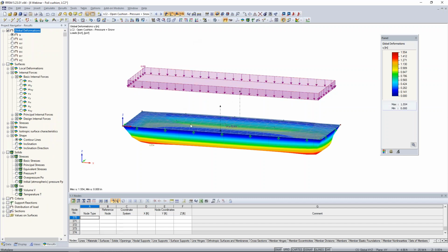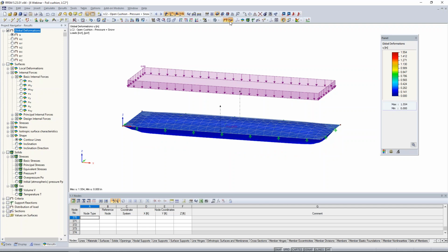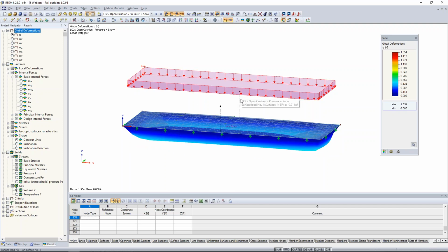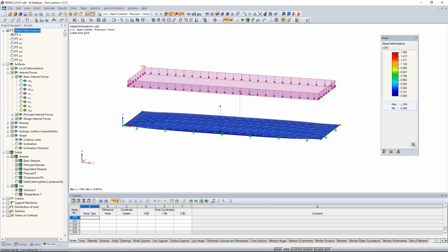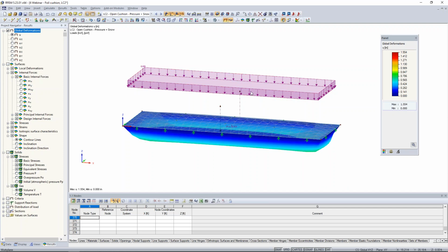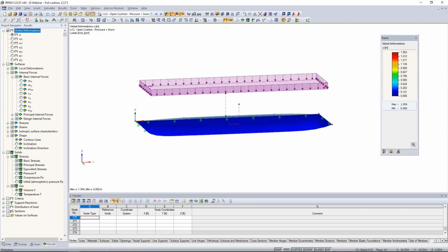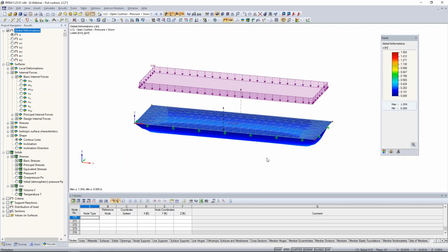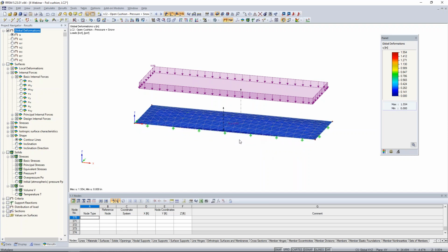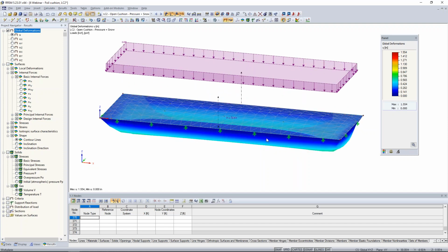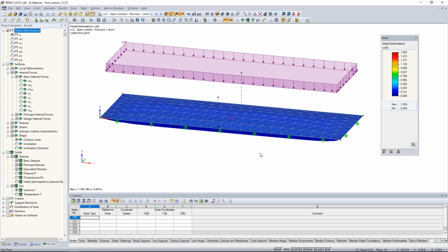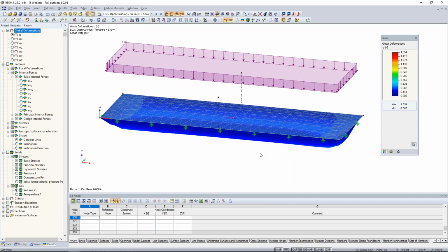downward deflection of our entire system. So what's important to note here is that without this gas solid defined, if we were to apply an area load, well, this would just be applied to the fabric membrane on top, and it'd probably pass right through the bottom fabric membrane. But as we have it defined now, well, we have this interior solid with gas properties. So both of these elements are actually deflecting together. So quite powerful, again, in how we can use a gas type solid.